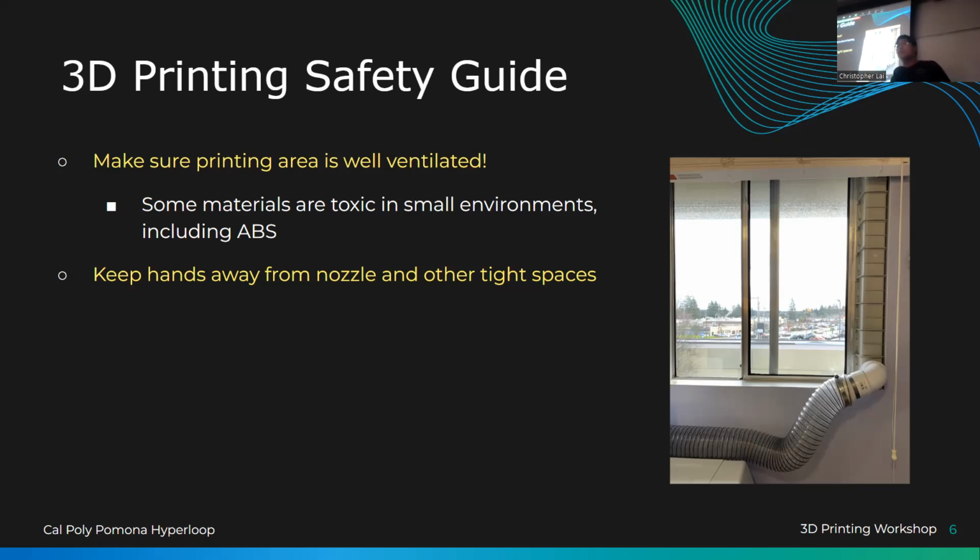During the escape room, one of the things you're going to do is install a new nozzle. Now, installing a new nozzle on a printer happens for a couple of reasons. One, when you're printing, your filament gets stuck in the nozzle and doesn't want to go through. Two, when you're printing, you notice there are some defects in the flow, or how much plastic is going through the printer at all times. Three, you're being placed in an escape room and you want to use the nozzle to help you escape.